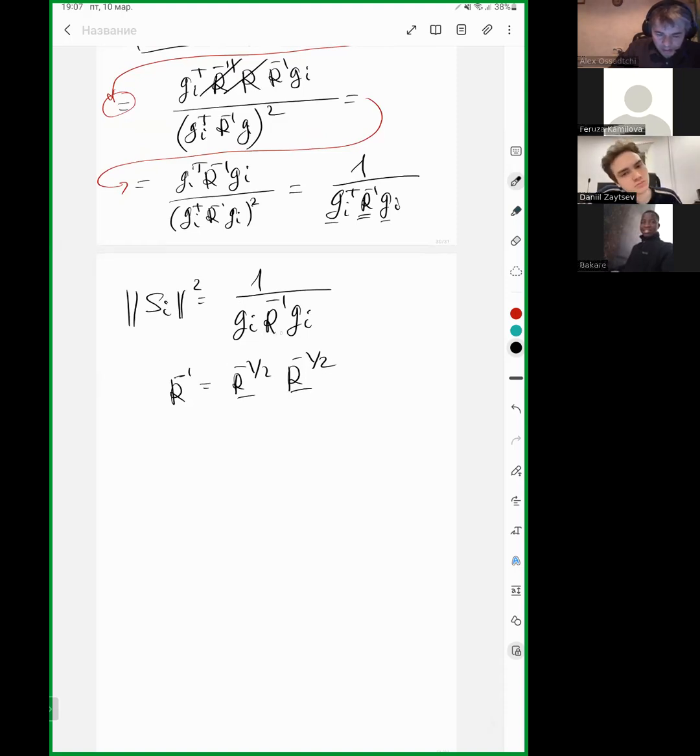you are looking basically at the norm of your GI with respect to this matrix that transforms the space to make it spatially white, right? To make the data in the space spatially white, right? And depending on how much you need to transform it, you can make a judgment about the presence of this or that source. Okay, that's essentially what this beamformer power distribution is.